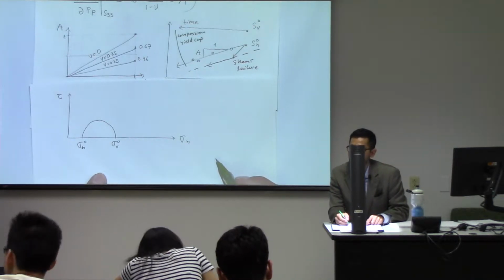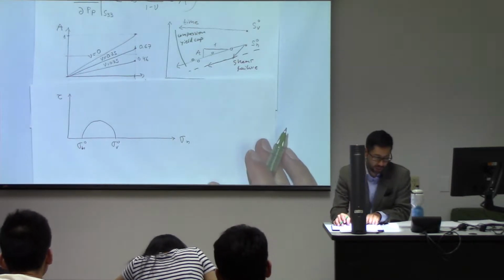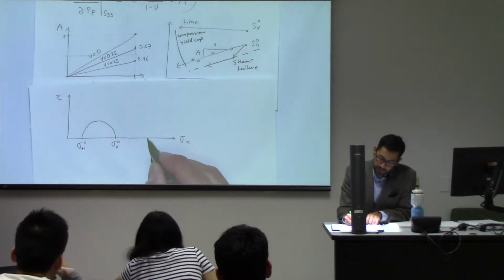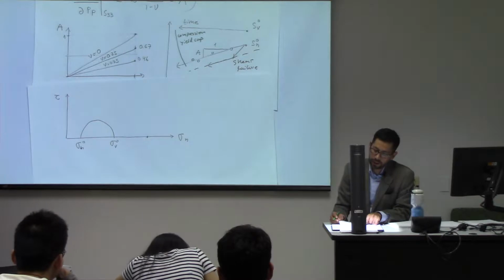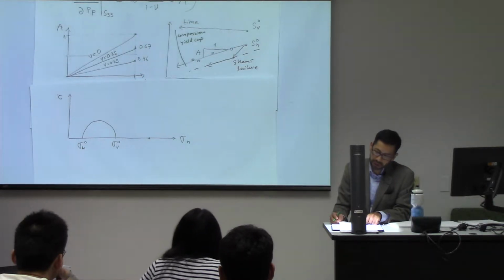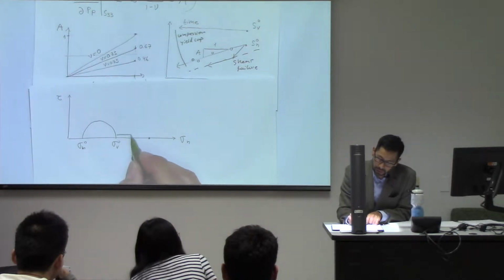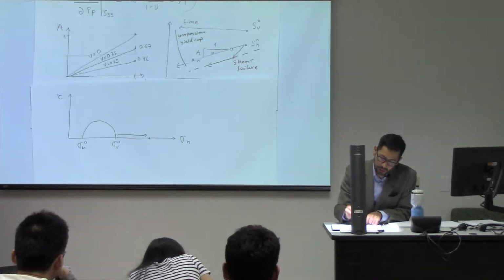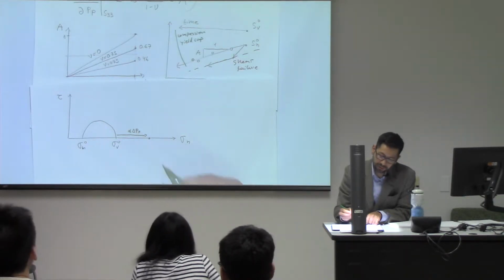Times alpha, right? Because we now have modified slightly a little bit our effective stress equation. If you change a magnitude delta P, the pressure, and in this case we're reducing pressure, if we reduce the pressure, the vertical stress is going to increase by an amount alpha delta pp.